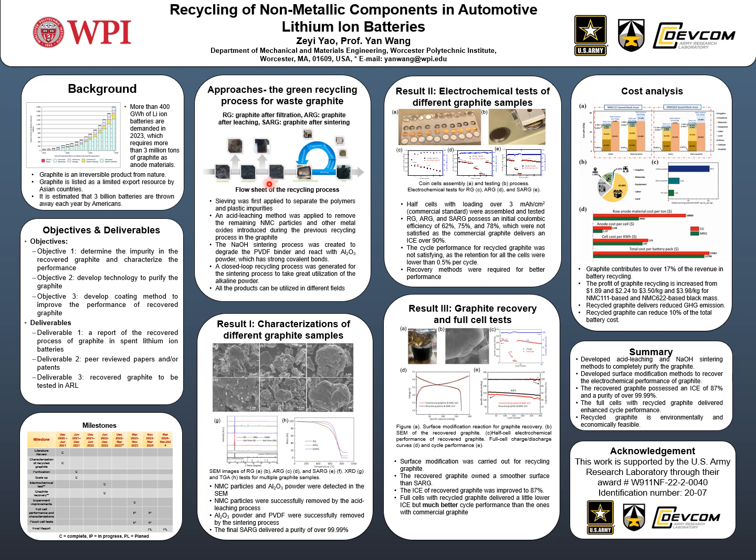Finally, because the strong covalent bond makes aluminum oxide hard to dissolve, we innovated a sodium hydroxide sintering process. By utilizing the high activity of molten sodium hydroxide, the impurities were completely removed. Notably, the excess sodium hydroxide and all the side products can be utilized in different fields. Characterizations were followed to confirm the successful purification process.